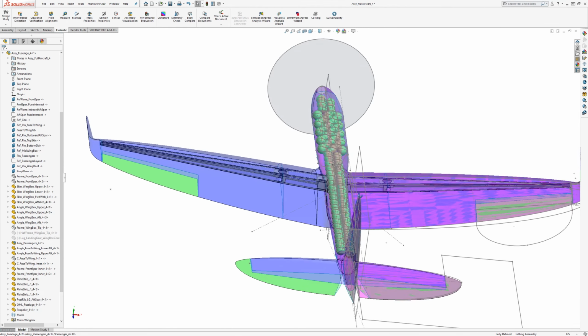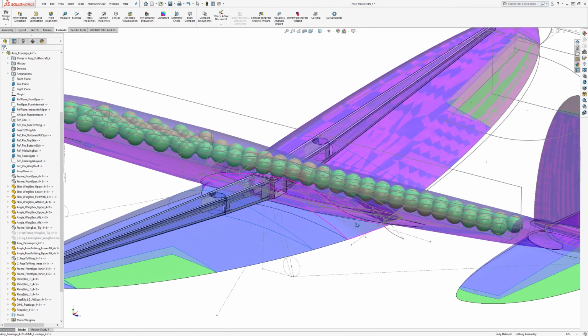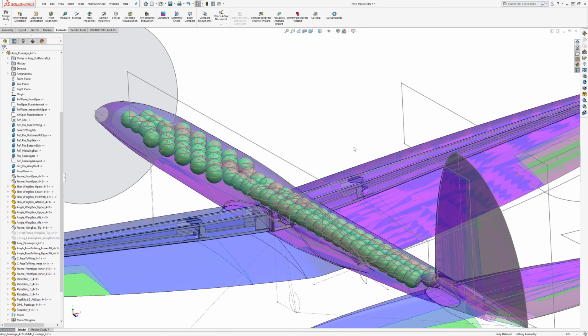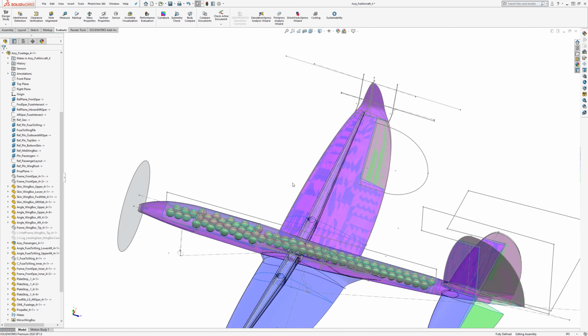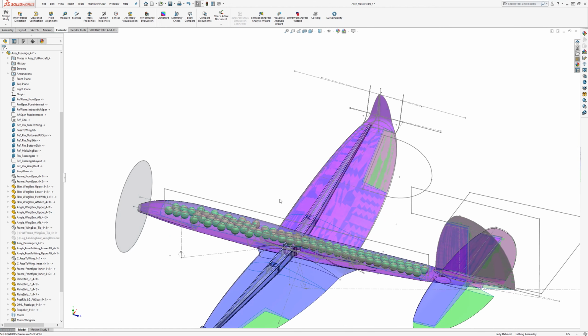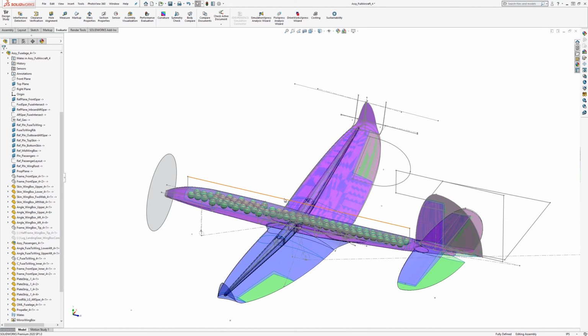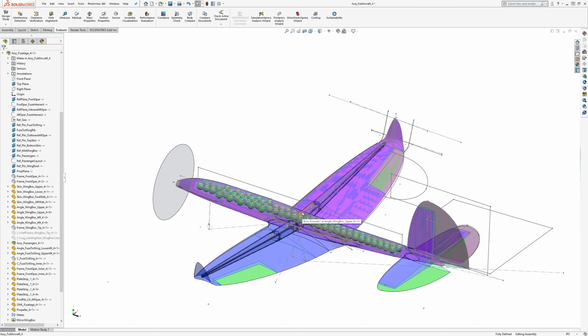Now, this aircraft has an elliptical planform. It has these winglets. This involved wing root fairings on a low wing configuration, and so those aren't features that are required for an SAE aircraft. Of course, each of those adds a bit of performance, but before going with a top-down assembly with surfacing with as many complications as this, I would make sure to be familiar with bottom-up assemblies of rectangular planform aircraft, then also assemblies of trapezoidal planform aircraft.